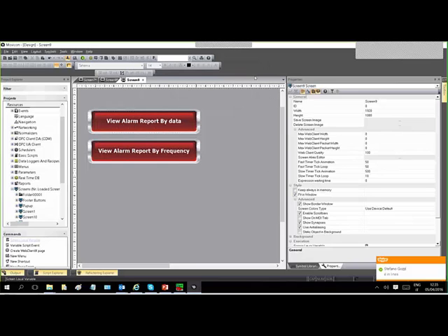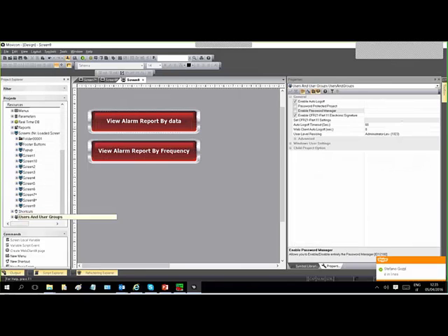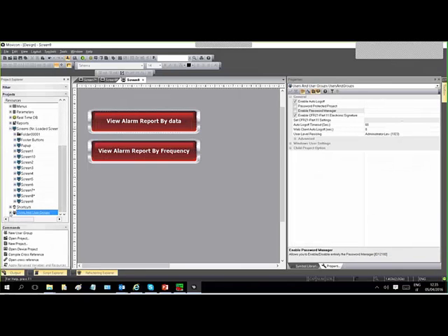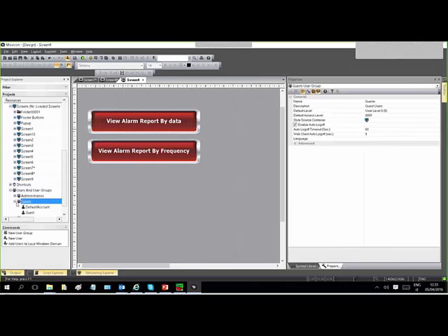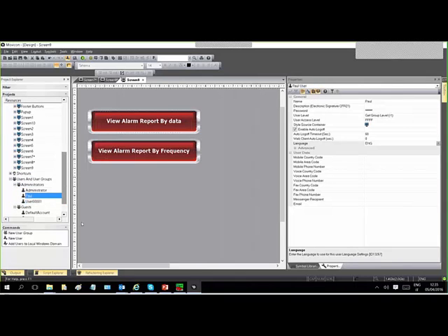This is the prerequisite. Then in the Movicon project, the first step is that the recipient will be a user. User 1 or Paul, for example. Let's say user 1. In the detail of the user, according to the plugin that you select, you should define the recipient, the mail.